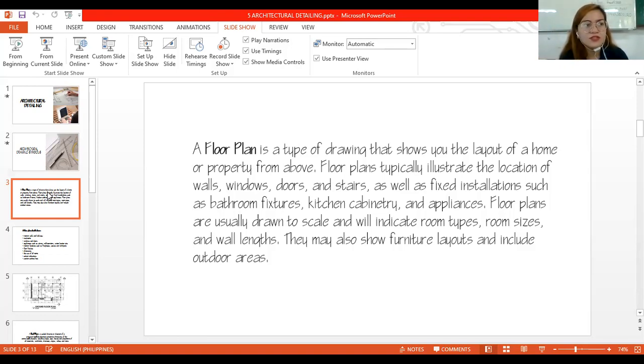If you're not gonna show it, at least indicate a symbol FF, that means floor finish, FF01, and then indicate it on the side on your paper, the legend. So if FF1 is tile, write it on the legend. FF1 ceramic or homogeneous tiles, then the specifications and the dimensions.